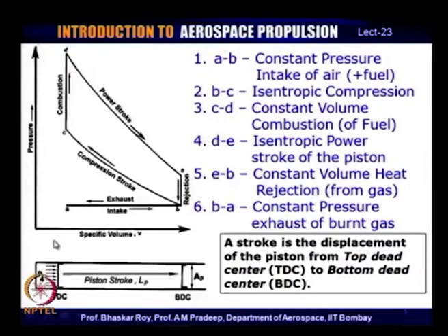out through this port into the outside of the system, and then the fresh charge or fresh air starts coming into the body of the cylinder. So, this is how the cycle occurs. The fresh air comes in, timed to open exactly when the air is supposed to come in. Once it has come in, this port is closed down, and then the process of compression starts, and then again